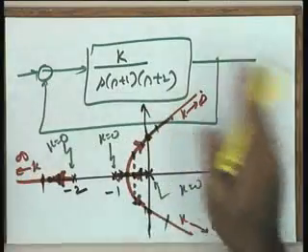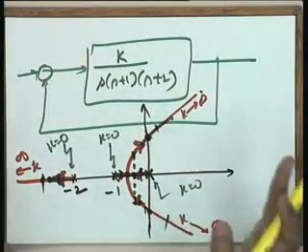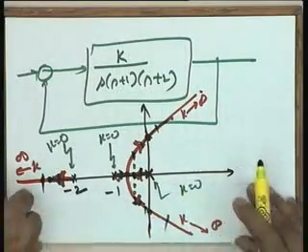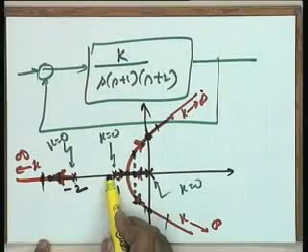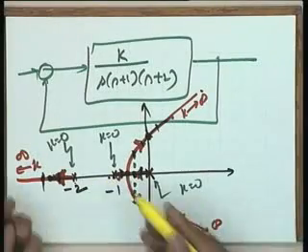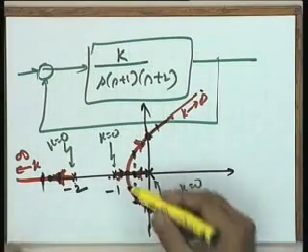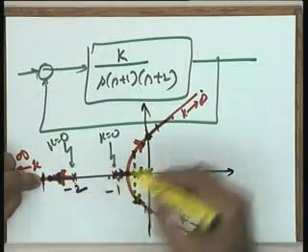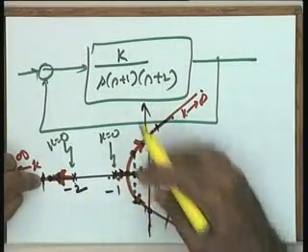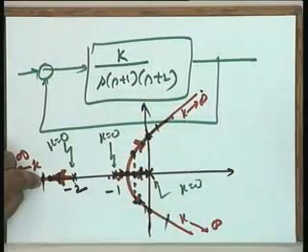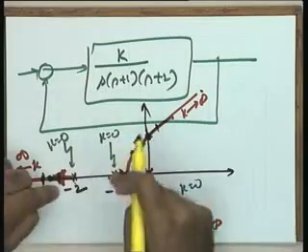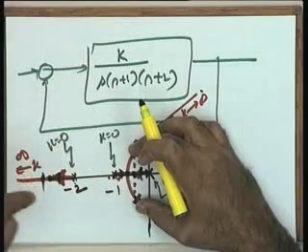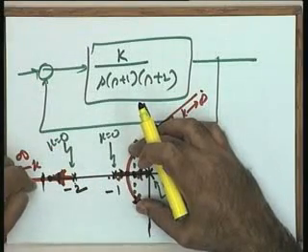So it means the root locus plot will give you that information as well. You cannot conclude that the third root does not affect the transient performance. Let me take a situation where this 0 is close to this. In this particular case, it depends. But I want to say, in general, you have to determine the third root and check the dominance condition. If it does not affect, then your performance translated into these two poles is the acceptable performance. And if it really affects, then the performance you have translated in terms of these two poles is not the true performance, and you have to suitably account for this effect as well.